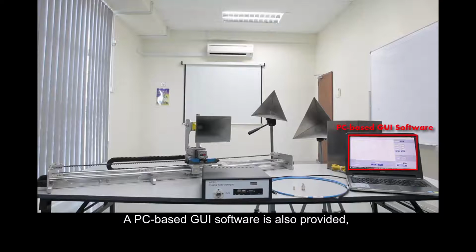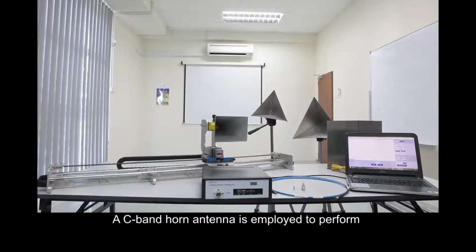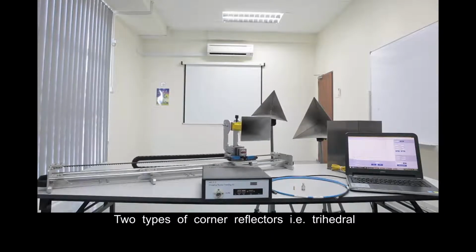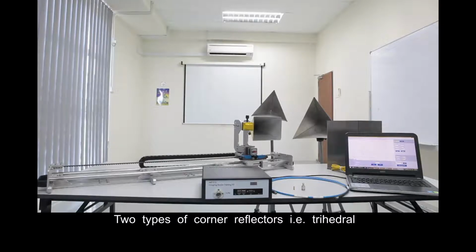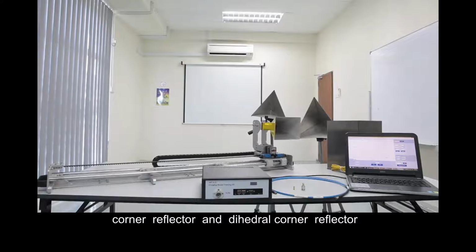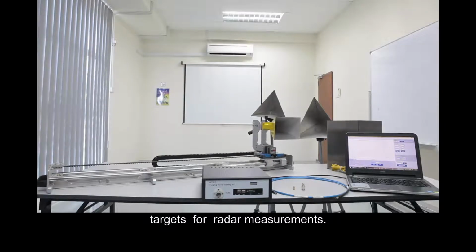PC-based GUI software is also provided, allowing the user to configure the radar for various operations. A C-band horn antenna is employed to perform monostatic radar configuration. Two types of corner reflectors, trihedral and dihedral, are included as external man-made targets for radar measurements.